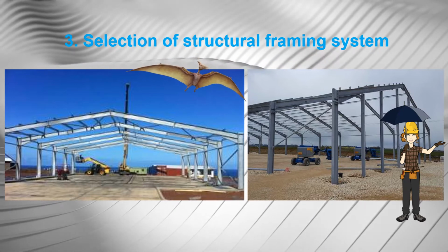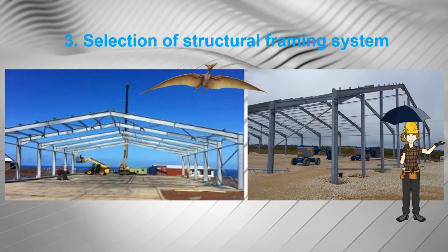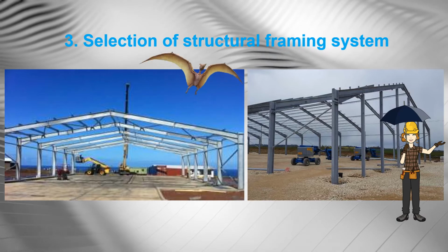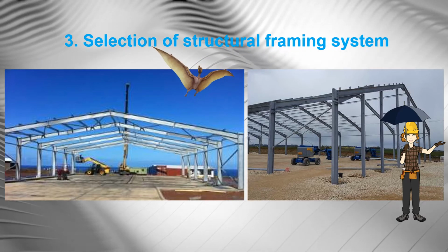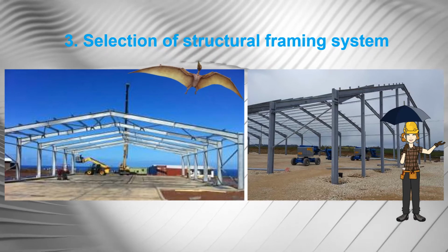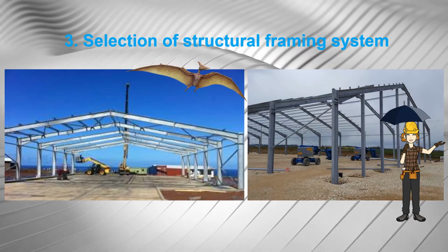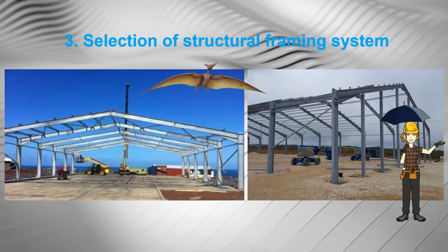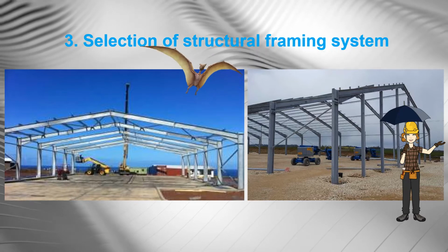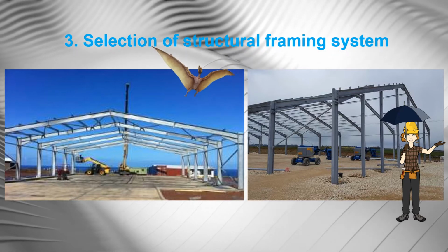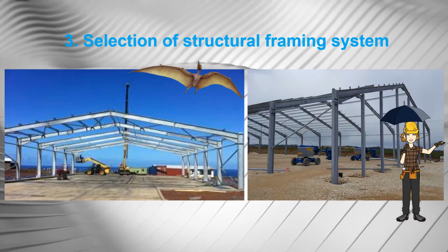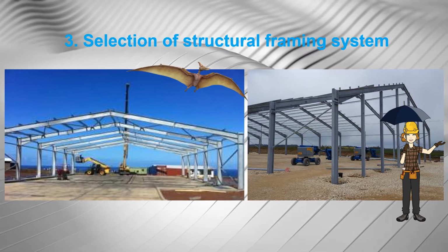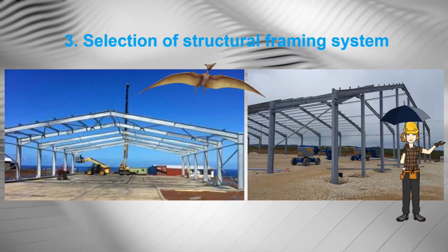However, the disadvantages include relatively high material unit cost and susceptibility to differential and temperature stresses. In addition, these frames produce horizontal reactions on the foundation, which may be resisted by providing a long tie beam or by designing the foundation for this horizontal reaction.